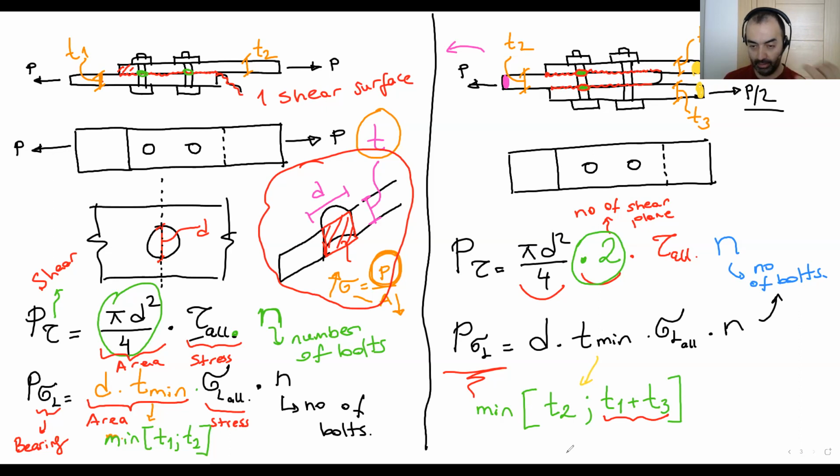And these equations give you the capacity of the bolts. So if you know that, the critical question for you at the end is P_shear capacity and P_bearing capacity. So the shear capacity of the bolts, total bolts, and the bearing capacity of the bolts.